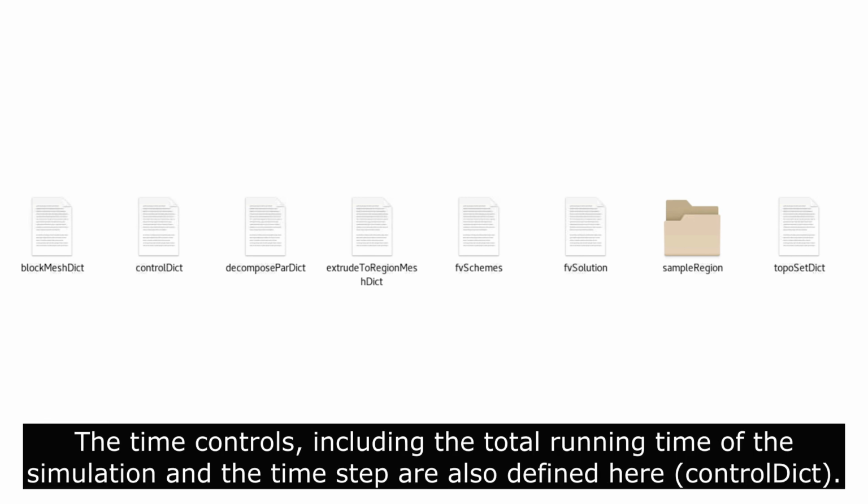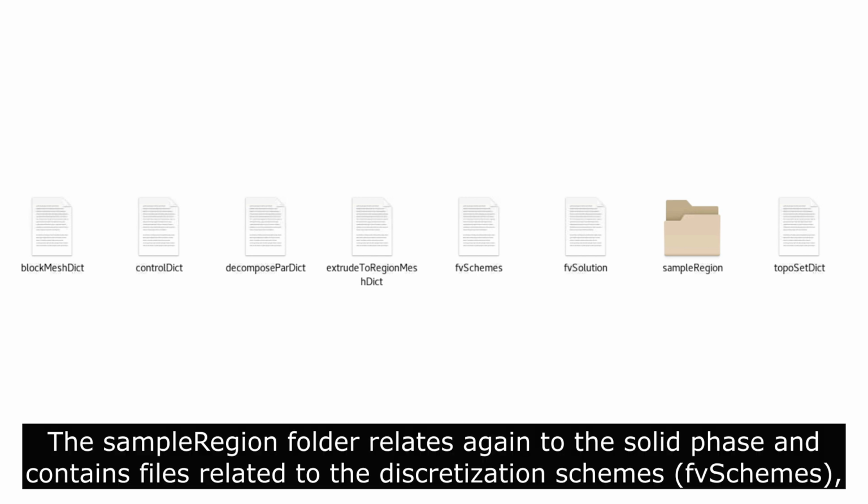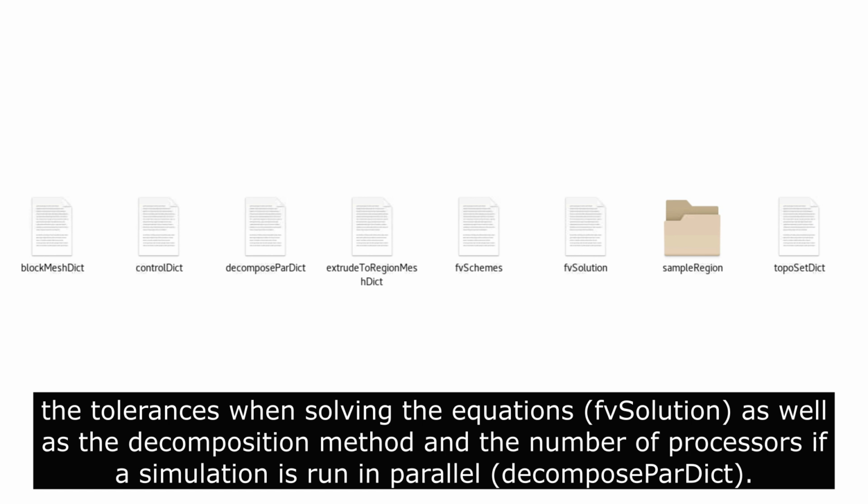The time controls, including the total running time of the simulation, and the time step are also defined here. See ControlDict file. The sample region folder relates again to the solid phase and contains files related to the discretization schemes. See FV schemes file. The tolerances when solving the equations. See FV solution file, as well as the decomposition method and the number of processors if a simulation is run in parallel. See decompose pardict file.